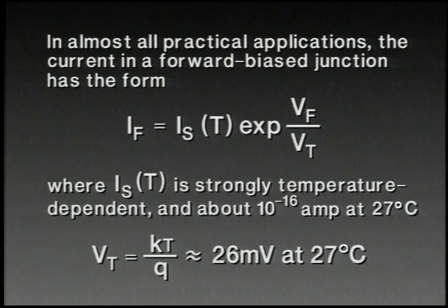The other thing worth noting here is that the forward voltage is first divided by the thermal voltage, kT upon Q, prior to becoming the argument of the exponential term. Now, if this were a discussion about, say, temperature sensors, we could spend quite a bit of time talking about some of the intriguing aspects of this relationship.